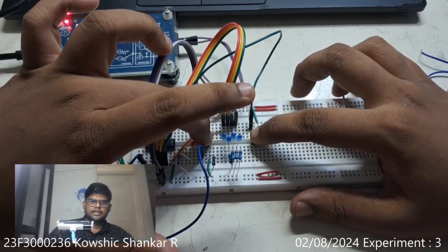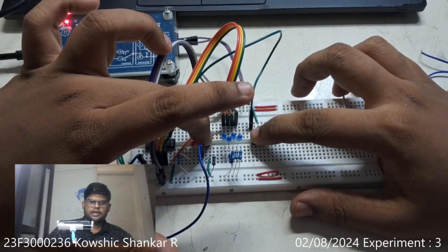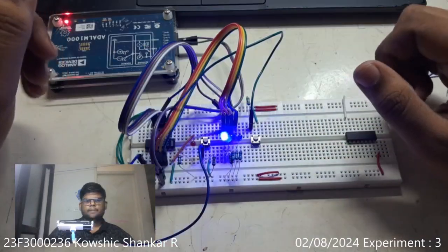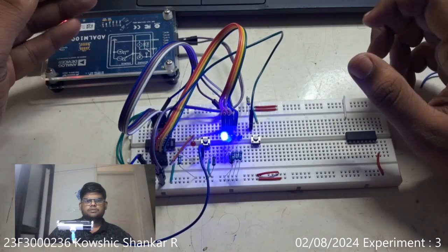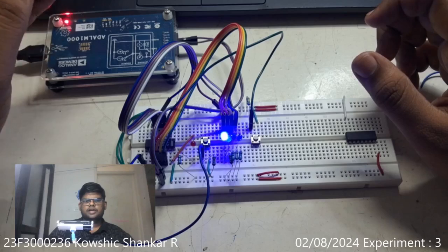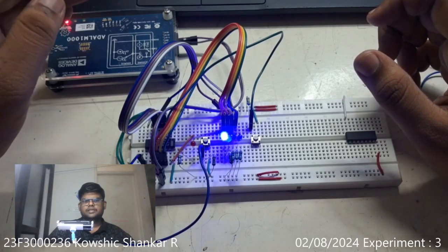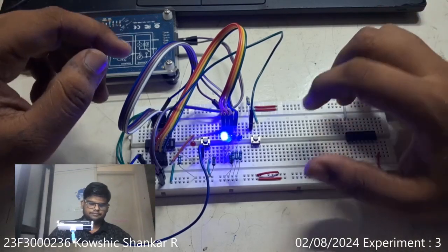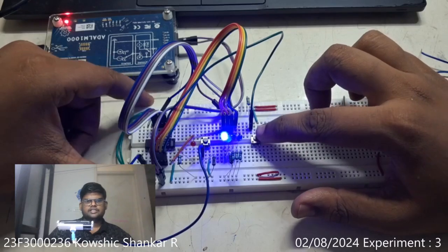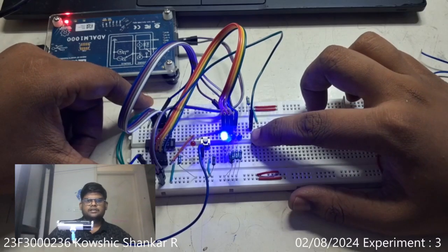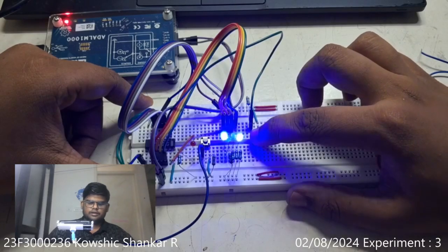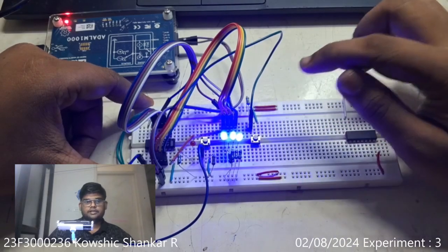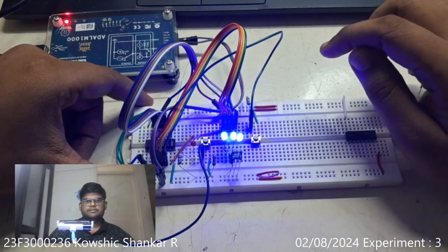So when I press the load and generate a clock, it simply outputs what is on the inputs A, B, C and D. In this case, it is 15. After loading the data from the inputs, if we count further, it counts from the number which we have loaded.